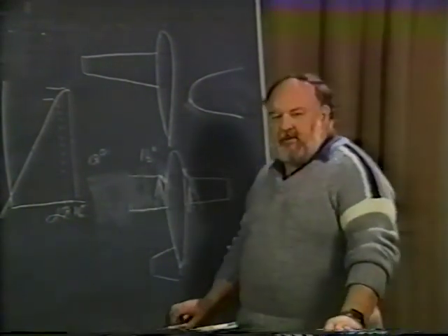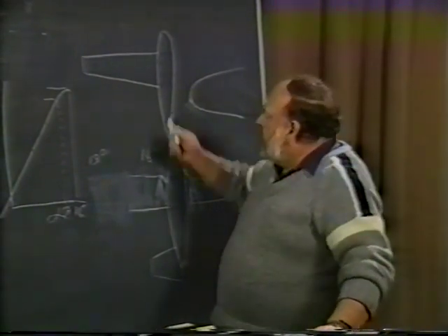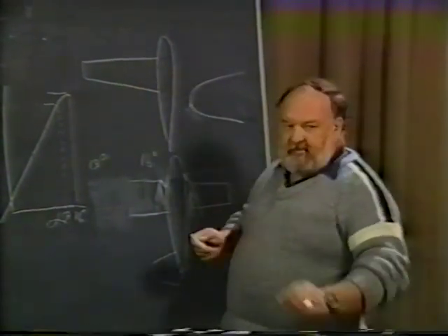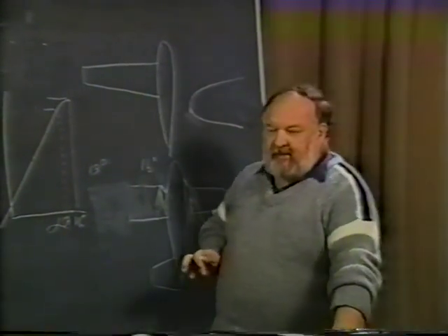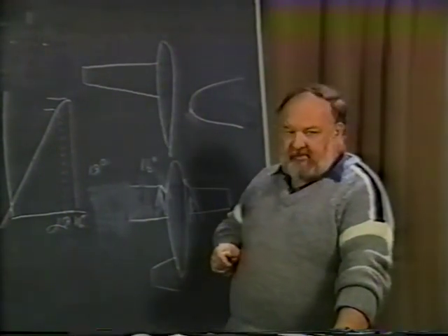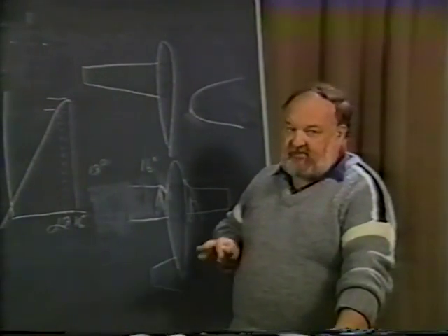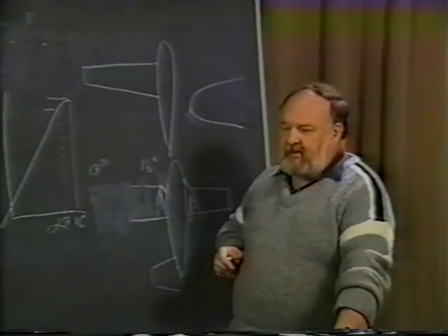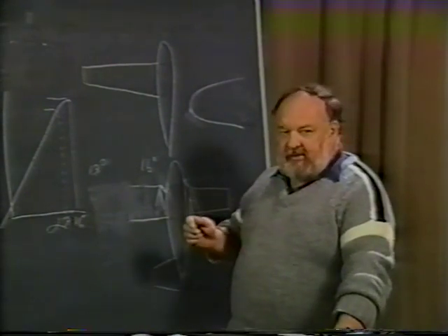Now, when we came to, say, an airplane like the Bede 5, we used a little different approach on that. We did use a tapered wing. It was a smaller chord at the root than it was at the tip. And we're well aware of the fact that this tip now had a lower Reynolds number. We're also well aware that this airplane was going to go quite fast, so we did not want to put any twist into the wing. But we still wanted to have a good stall pattern. Well, what was the technique that we used there?